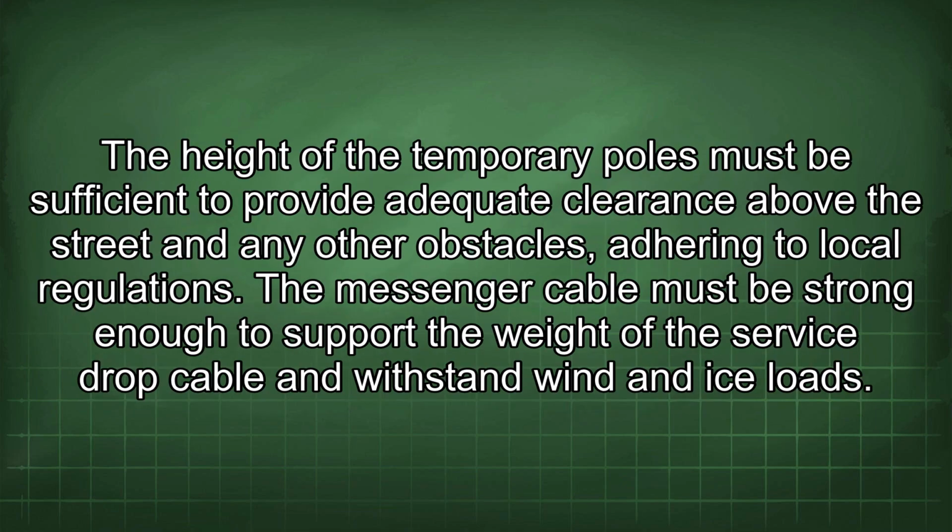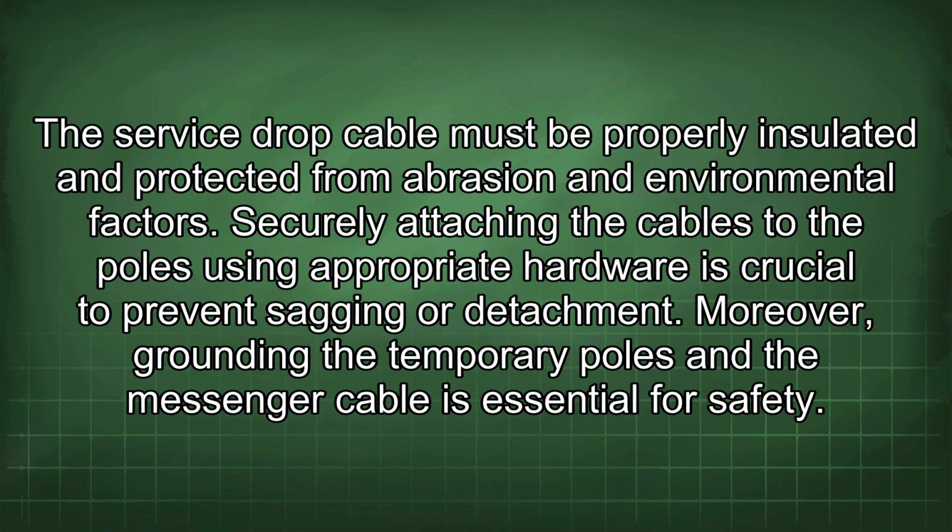The height of the temporary poles must be sufficient to provide adequate clearance above the street and any other obstacles, adhering to local regulations. The messenger cable must be strong enough to support the weight of the service drop cable and withstand wind and ice loads. The service drop cable must be properly insulated and protected from abrasion and environmental factors. Securely attaching the cables to the poles using appropriate hardware is crucial to prevent sagging or detachment. Moreover, grounding the temporary poles and the messenger cable is essential for safety.